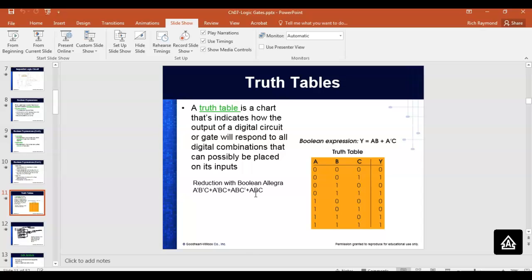When I worked at U.S. Steel, they bought a new electronic scale, we called it the line scale. And when they bought the scale, they didn't buy an auto zero. We like these big scales to have auto zeros because trucks are constantly dropping stuff. So over time, the scale would actually be weighing 1,000 pounds when the truck wasn't on there, just junk that was dropped on the big scale, right? So big scales like that, we like to auto zero it.